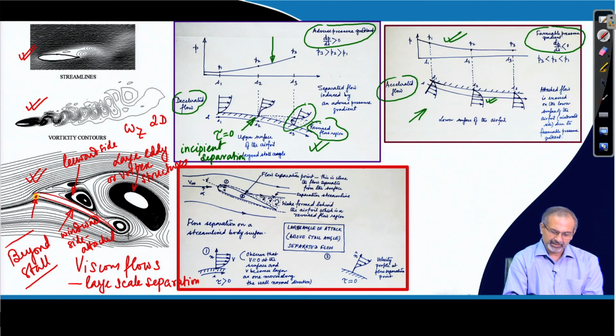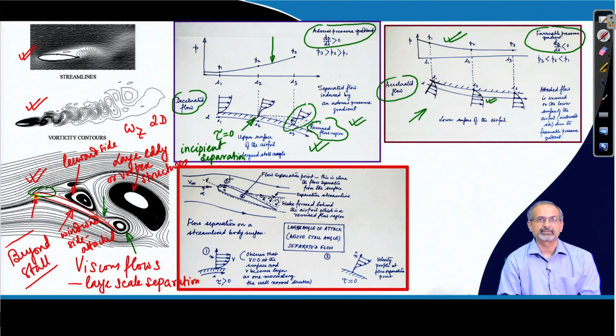So, all that once again comes back to you when you look at the numerical results. Here you can see large pockets of separated flow where it has even gone beyond an ordered structure like this, because very close to the leading edge itself the flow seems to have separated. So, it is like a leading edge separation which is in action currently.